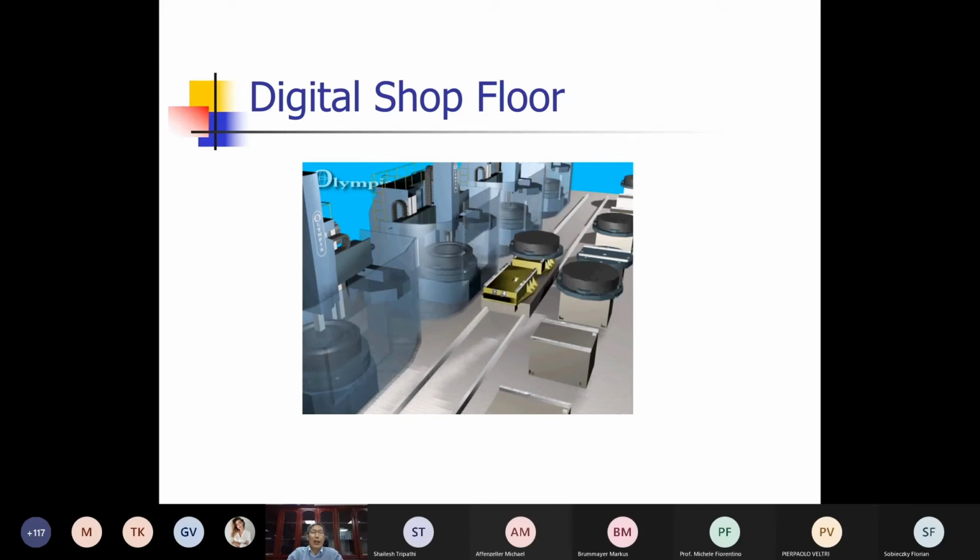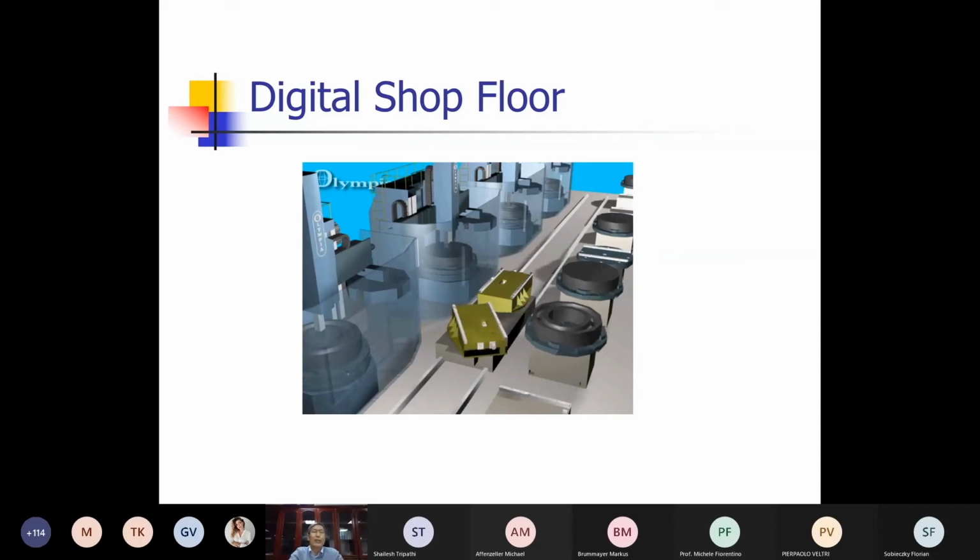So the idea of implementing an autonomous agent-based system is to model each machine as an agent, and also the rail cart in the middle as an agent, so that they can work autonomously or independently. If one machine fails, say a tool is broken, only that particular machine stops, because they are loosely coupled. So each machine can stop and the rest of the system can continue to work. The other 3 machines can even negotiate to see who can finish the work initially assigned to the machine that failed. We finished the development of the concept and the system, and the company implemented a loosely coupled system so that the 4 machines can work independently without intervention from other machines.